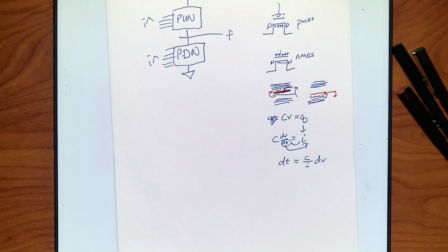Now you've got this lovely little differential equation, and you get this time constant, which is related to RC. If I get a very small resistance, I can have the current growth, but the bigger the resistor to keep from getting too much current flowing, the slower the system is. And you can directly calculate it because it's proportional to RC, right?